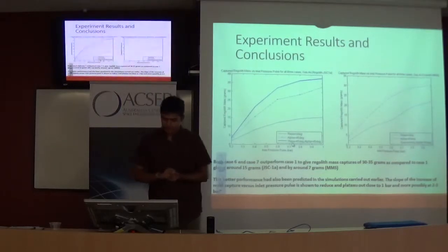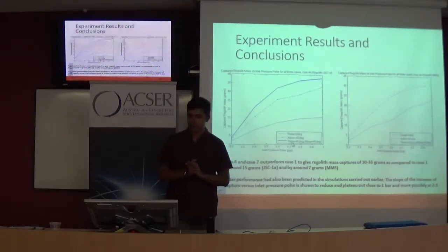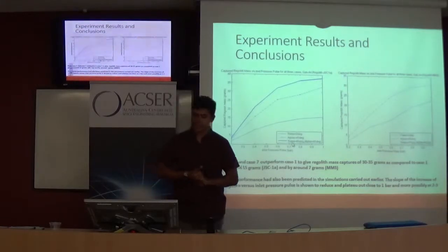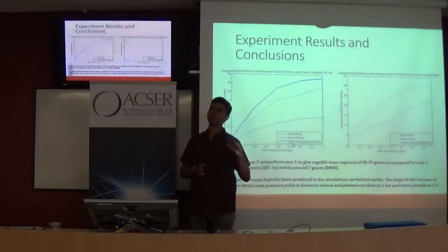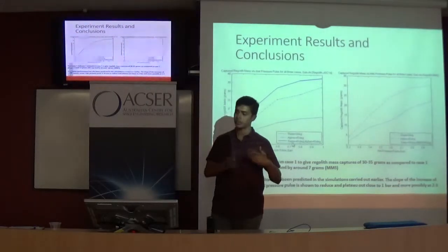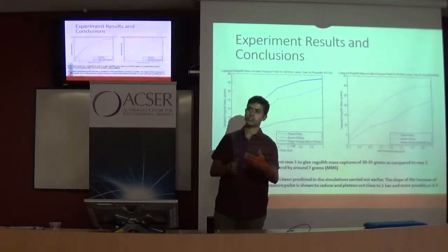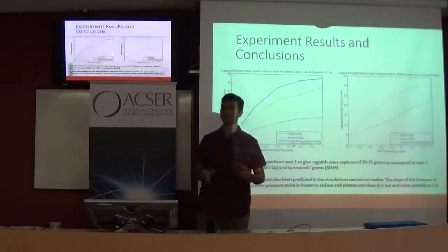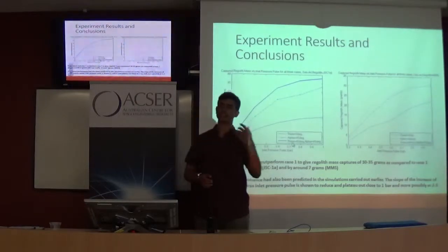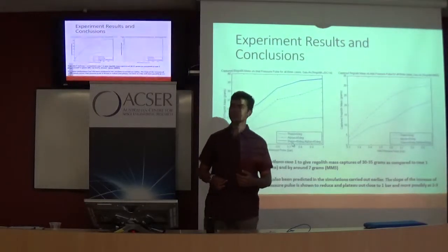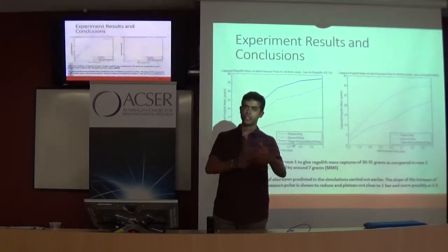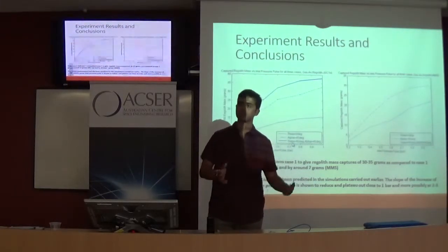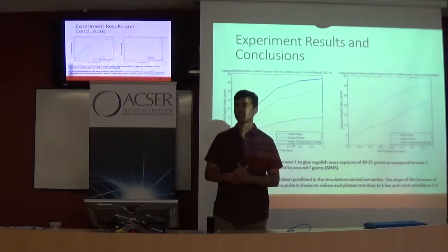Yes, so here you can basically see the comparison between the experiments where I was able to get different pressure pulses. So I was pulsing different pressure values, and this is only between 0 and 1 bar. So within 1 bar of gas pressure itself, I was able to collect a certain amount of regolith samples. Is that the maximum? Not really. This is just to show that within 1 bar itself we were able to collect certain samples.